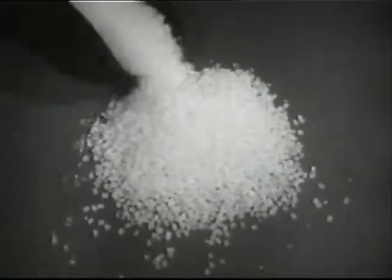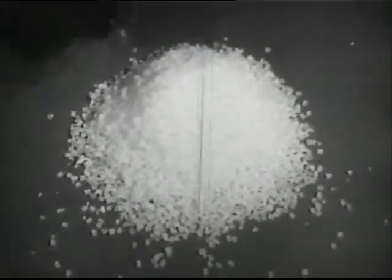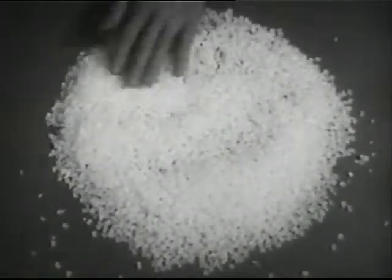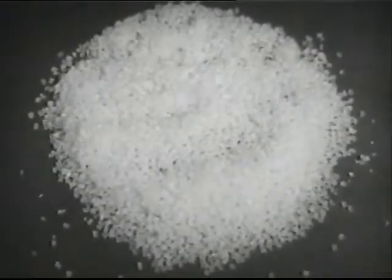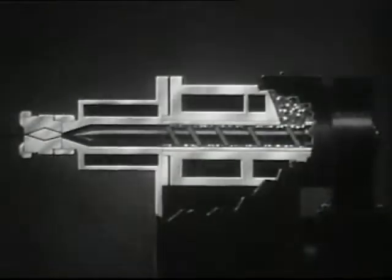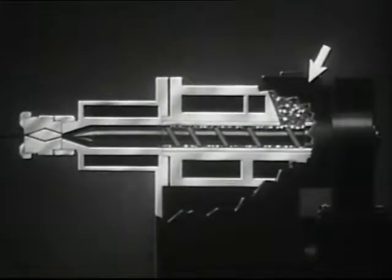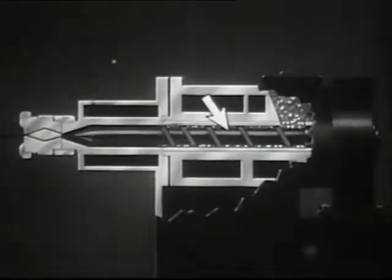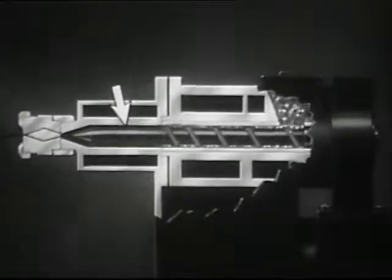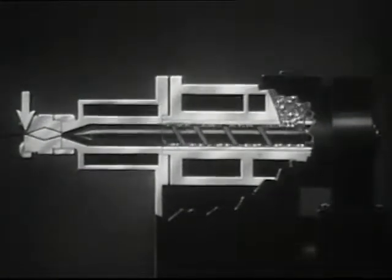This time, polystyrene is used with no dye or fillers because the dial must be transparent. The dial face is to be cut to size and shaped from sheets manufactured by another process known as extrusion. Here the material is placed in a hopper. Then a continuous screw forces it into the heating chamber. Heat and pressure soften the material, and it is forced out through the die opening in hot plastic form.